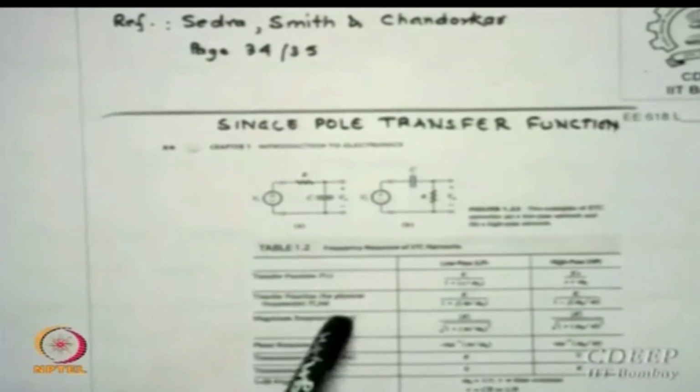If you write in T(j omega) form, s is equal to j omega, substitute there and you get this value. The magnitude response, which is essentially taking the magnitude of any complex function, a plus jb, is the square root of a squared plus b squared, and its phase is tan inverse of b by a. So that's the standard technique which we have been using for complex systems for the last 3 years at least in IIT and maybe many years earlier. So we are interested in two responses of any transfer function.